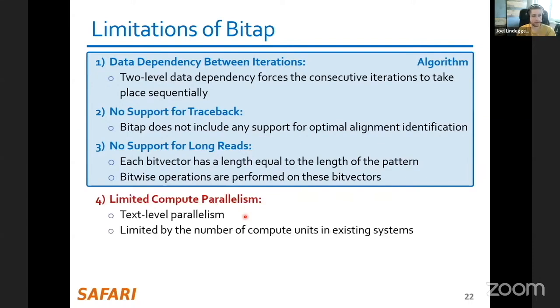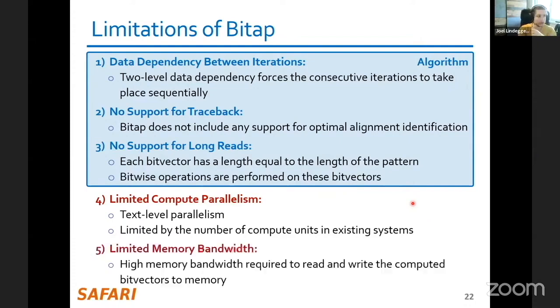Now there's also implementation level inefficiencies where you really want your hardware to do a good job at executing this. And basically observe that there's a limited parallelism in the algorithm as well, but that means this really affects hardware because you have to have your hardware go sequentially over all entries. And then you will have a limited memory bandwidth. So if you have this huge table and you frequently access all of these entries, then you have to spend most of your time just moving data instead of doing computation.